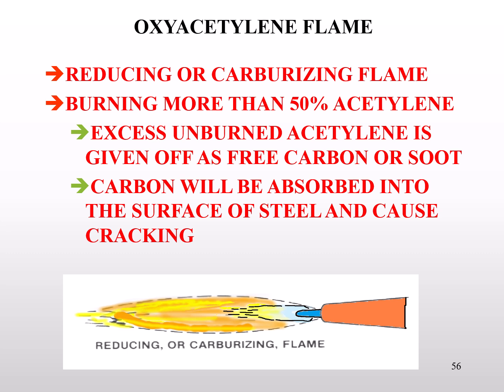There are places where a reducing or carburizing flame is desirable. Some stainless steels like a little extra carbon to help them restore that stainless property, or anti-corrosion property. Welding them reduces that, so adding a little additional carbon back helps the material regain that particular characteristic, but it's not often used outside of those particular uses.